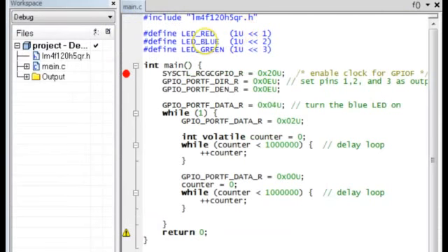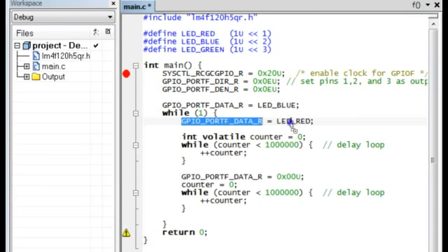After defining the macros for the LED colors, you can replace the cryptic hex numbers, which greatly improves the readability of your code. In fact, your code becomes self-explanatory and the comment becomes redundant. Now let's tackle the really interesting case of setting the red color bit in the GPIO-F without extinguishing the blue